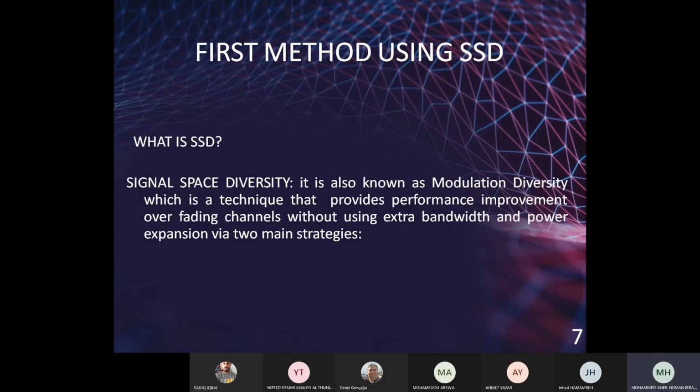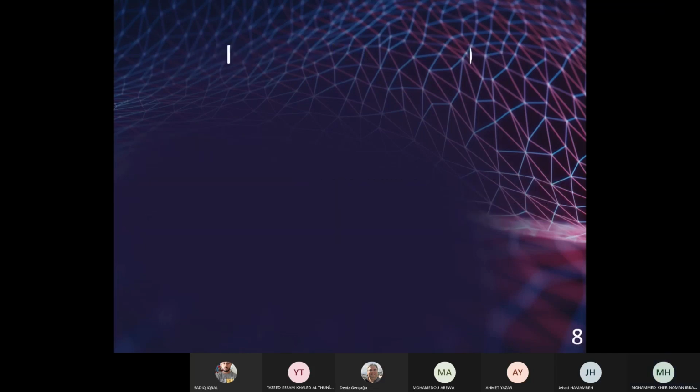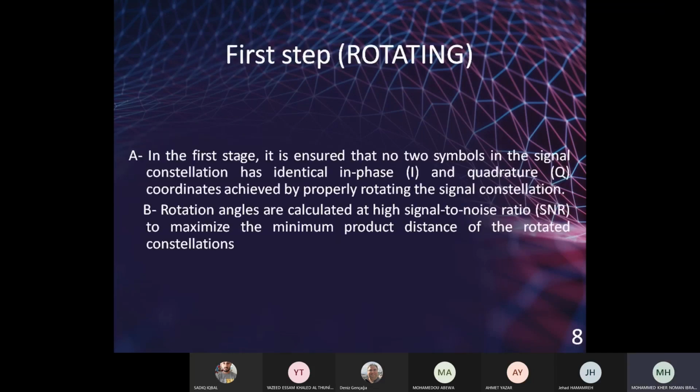The basic concept of SSD is the multidimensional signal constellation used and the components of each signal constellation point that are transmitted over independent fading channels. The independence of the fading channels can easily be accomplished by interleaving.